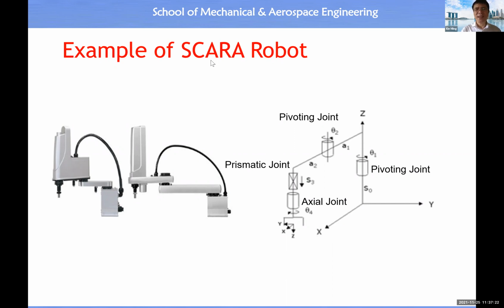We call this a SCARA robot, because it has 2 horizontal links which can only move in the horizontal plane. This robot has a vertical link which can undergo linear motion in the vertical direction. And the last link could eventually undertake rotational motion about this vertical axis.